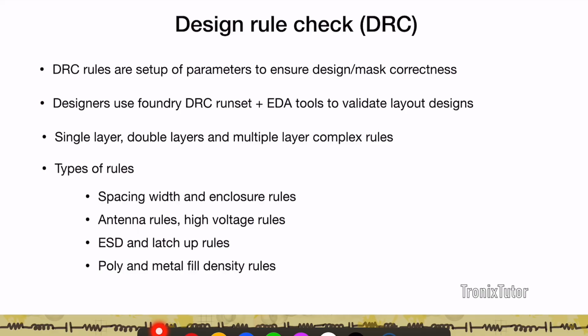You don't want them to be too close by because you run the risk of shorting, you run the risk of high capacitance, and you don't want the metal lines to be too far apart because then you're going to lose area. So there's always a certain spacing rule, for example, between metal lines. Similarly, you have rules for width, right? For example, if you think about a metal line, for a given technology, based on the particular kind of process they're using for deposition of the metal, it dictates what the aspect ratio of the metal